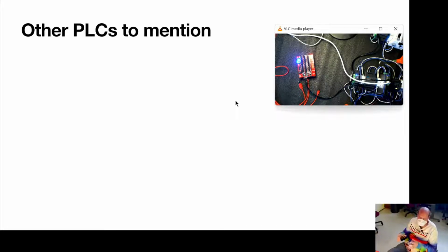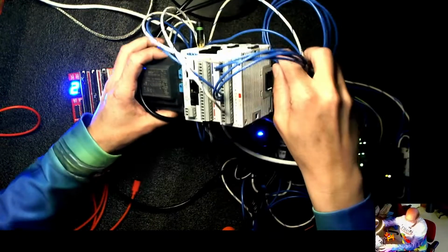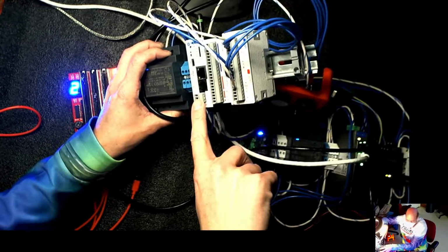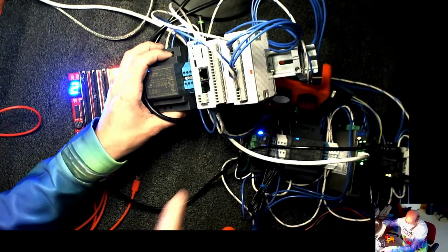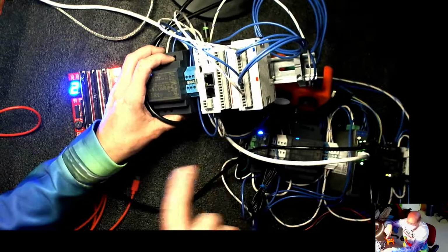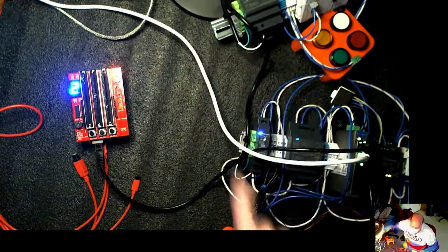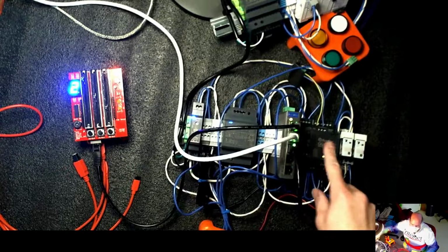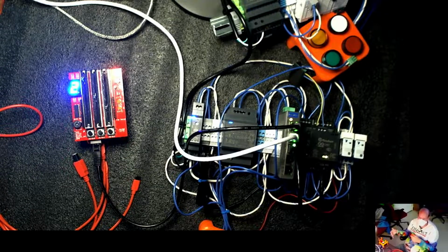Additionally, they are built to withstand vibration and higher temperatures. So typical cabinet ratings, I think, are 85 Celsius, and there's some vibration G-force rating. And they're also meant for in-circuit cabinet installation and maintenance and replacement. So the Click, for example, has all of the connections on terminal blocks that unplug. So if I blow up this module, I can pull it off, put another one in, and then connect my entire set of connections at once. Whereas some other PLCs like the Opta, which is over here, have screw terminals where you need to mess with the individual wires. So more built for reducing downtime.